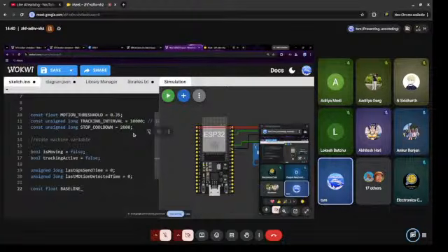The downward gravity is 9.81. The sensor measures this gravity, so our program compares the measured acceleration with 9.81. If it changes significantly, the object is moving.